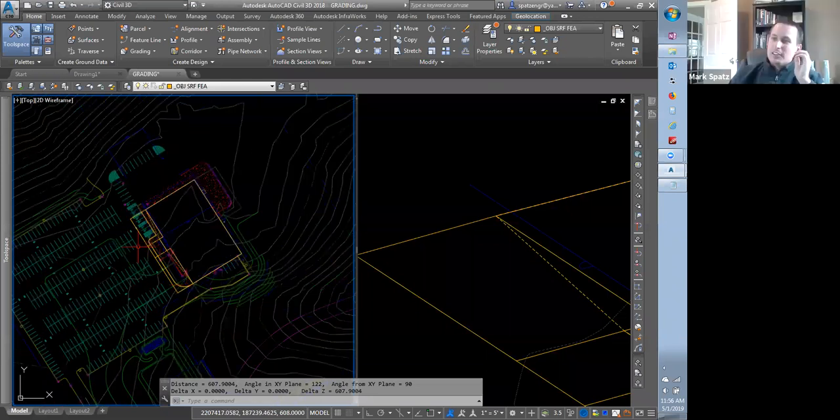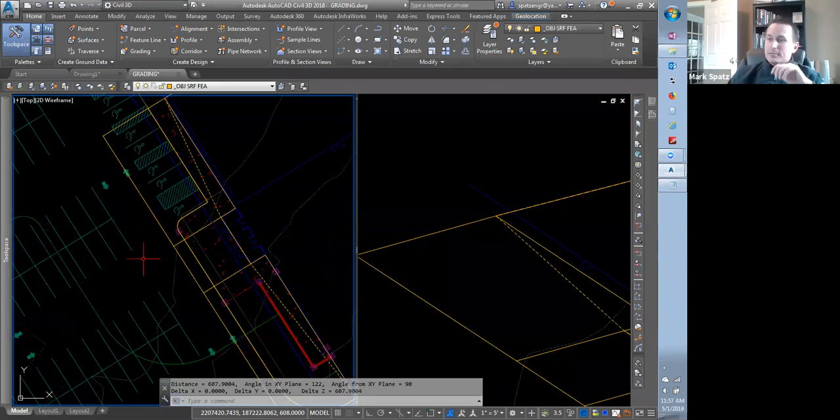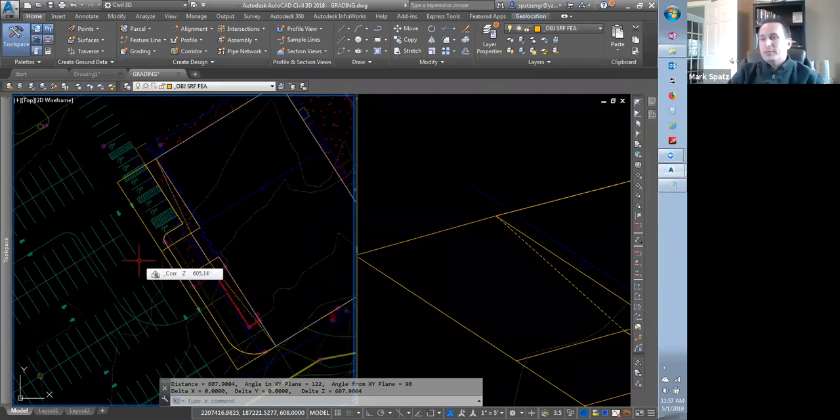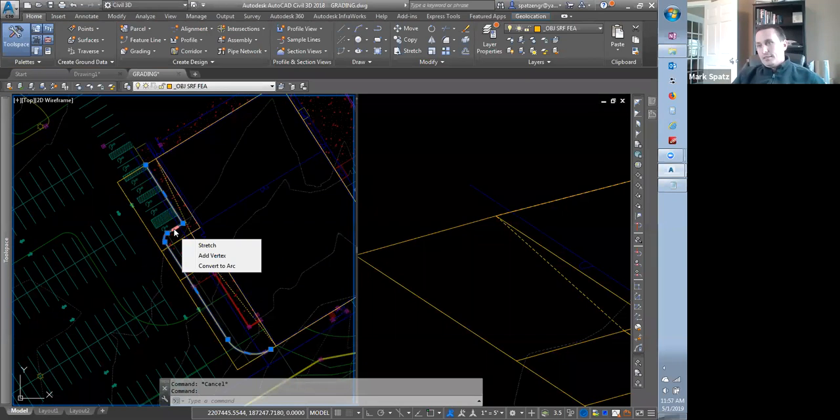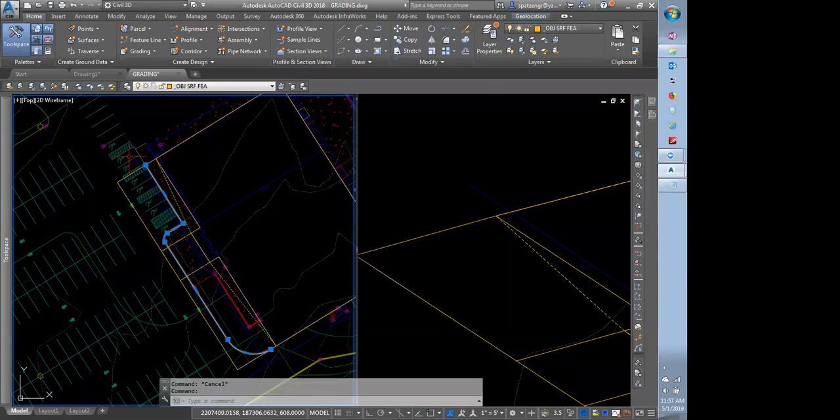Since we've overshot, we've extended that face out, I'm just going to trace in the rest of this curve top. Use a polyline edit command to join them together. One big top of curve face. Maybe that's how I should have done it to begin with. Let me know when you get to that spot.